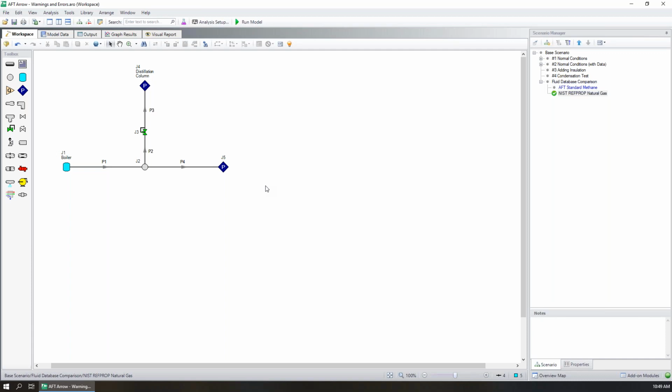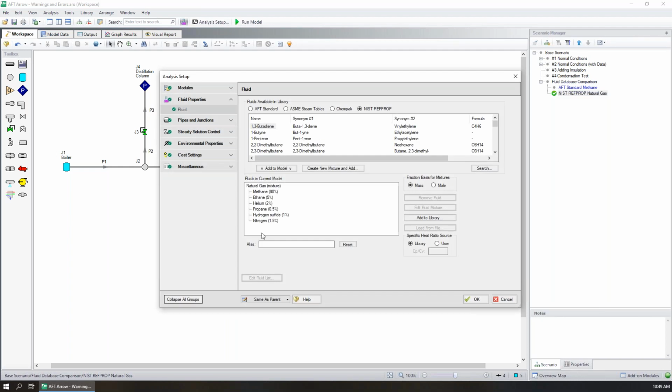And there's a few things that can cause that slow runtime and that gradual convergence. This fluid is a very typical case. You can remember this as one of our pitfalls, the others being parallel pumps or closed loops and detailed T's. So it's a good idea to look at a model, especially when it's running slowly and you're trying to troubleshoot and you're quickly iterating and experimenting, to look at this fluids, see if you can simplify it, and then that'll give you very good returns on your runtime.